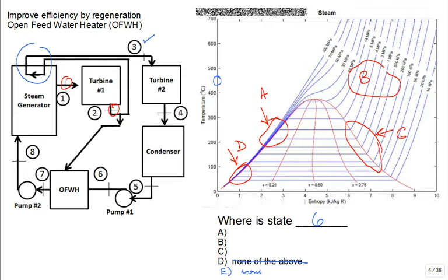Well, there's no pump between 2 and 3, is there? It just goes to a heat exchanger called reheat. So 2 and 3 have the same pressure. We have an ideal system that if you're going just for the heat exchange, like in the condenser, and the first pass through the steam generator or the reheat, those don't have pressure gains or pressure drops. They're essentially the same pressure.